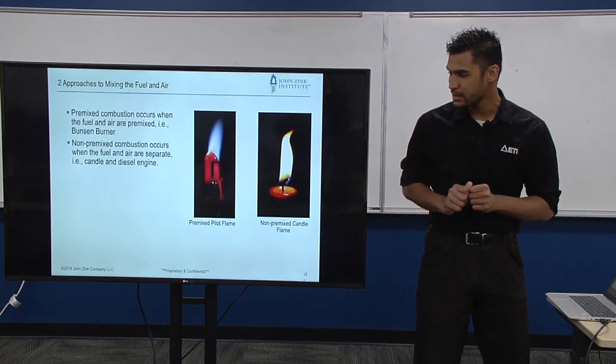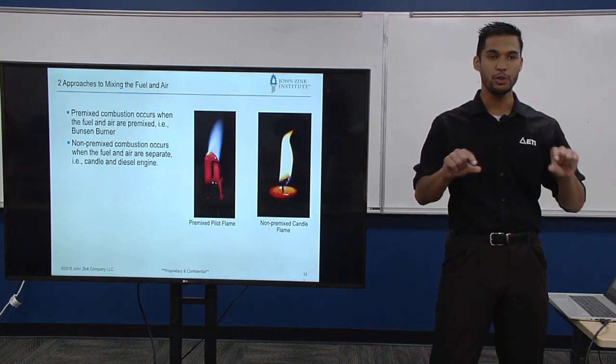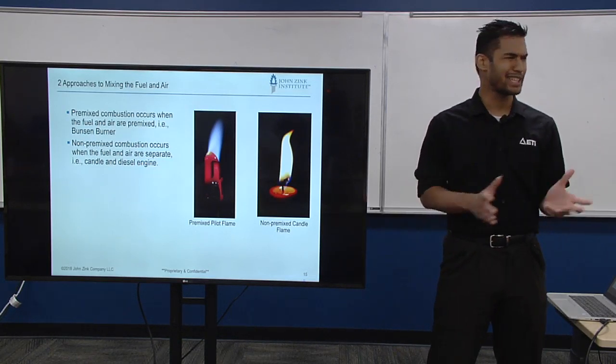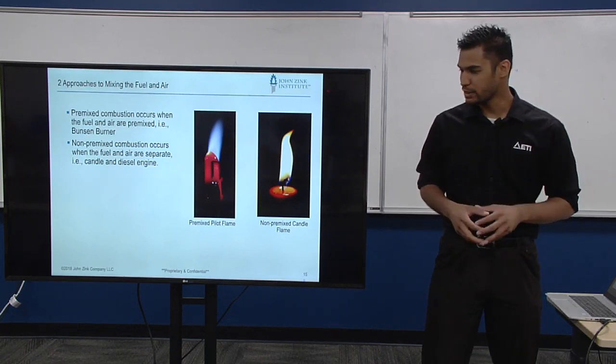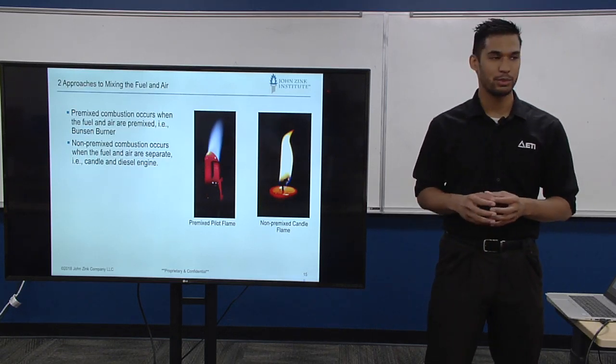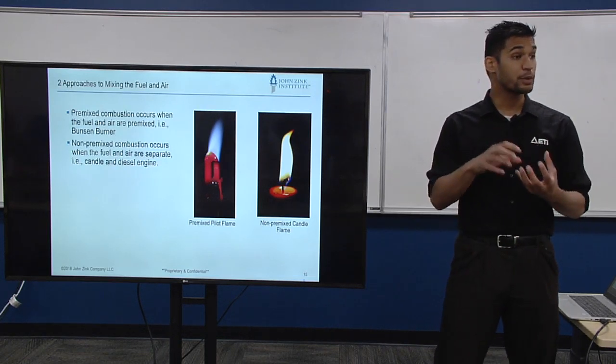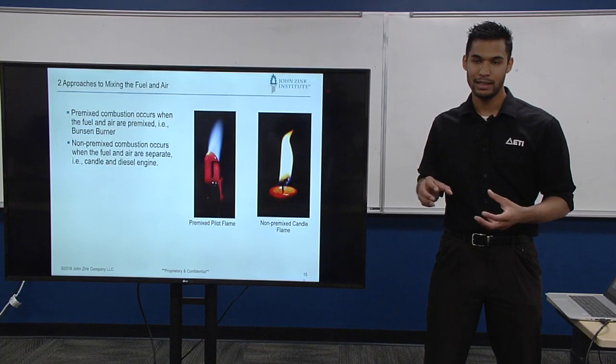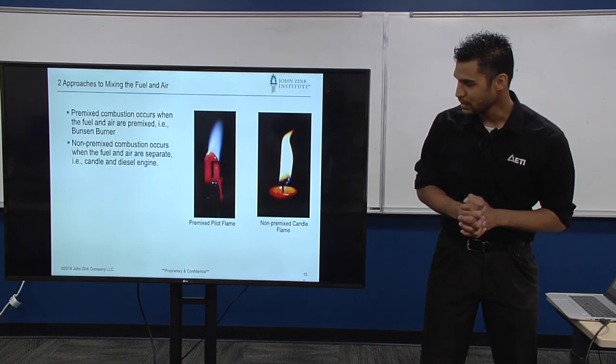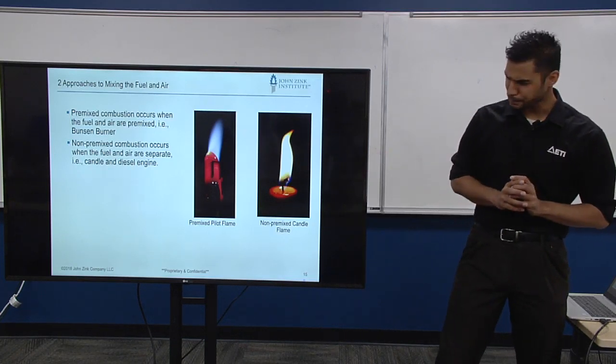We have a pre-mixed pilot flame where down through a tube I've taken my air and my fuel, just like a Bunsen burner, a little bit different. There's some stabilization mechanisms and geometry intricacies going on the inside that we can talk about later. But I'm pre-mixing my air and my fuel, and then I'm letting it burn. Okay? Notice how it looks visually.